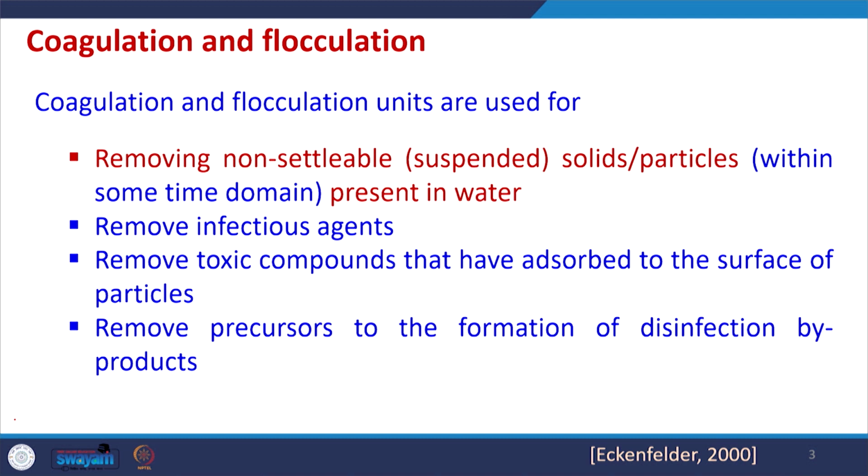Now, studying further, coagulation and flocculation units are used for removing non-settleable suspended solids or particles present in the water. So, we want to remove the non-settleable suspended solids or particles which by themselves do not settle down, and the reason may be that their density is smaller or their size is very small. If either of these two factors is present, that is, the density of the solids is small and or their size is small, they will not settle down.